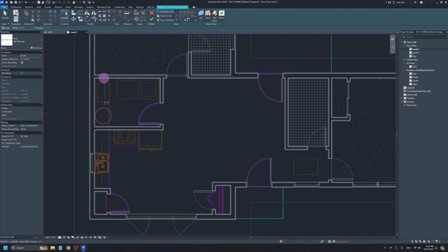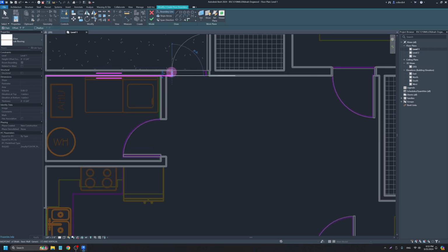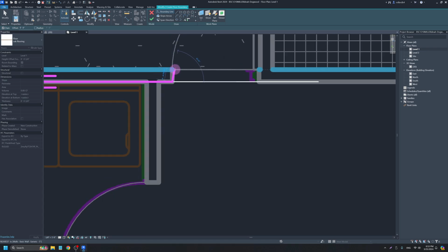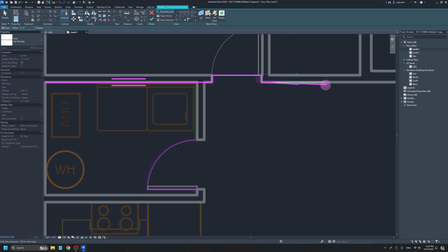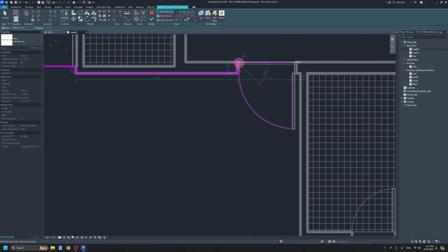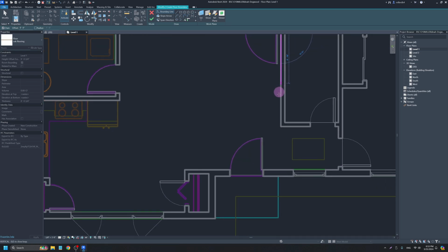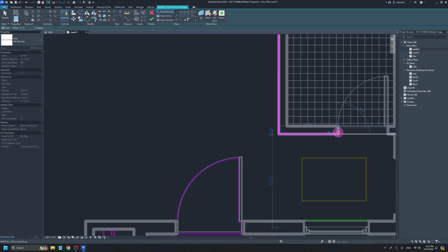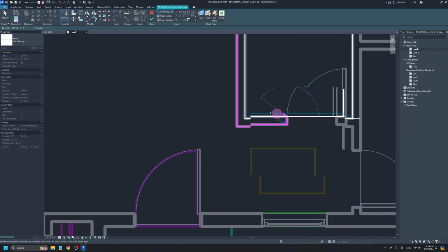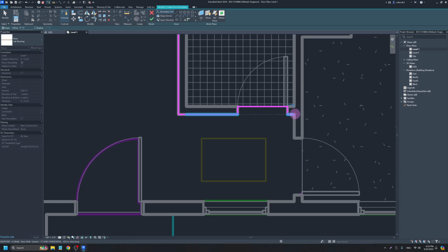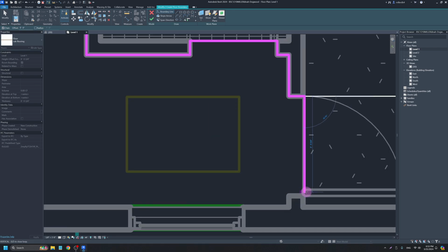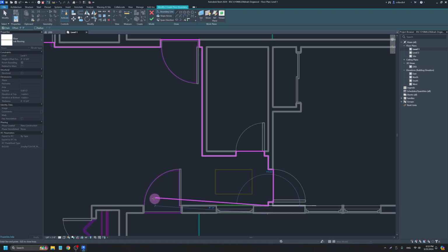And now I'm going to just trace around all of my areas that I haven't put a floor in yet. And sometimes this could be a little laggy to try to get them to snap to the places you want. Not sure why, just how it is sometimes. And I could have brought that tile out if I wanted to instead of using the rectangle tool. Same, I could have brought this carpet out. I just don't want to have any awkwardness, which I might have a little warning that says I have an overlap there, but I'm not going to worry about it.